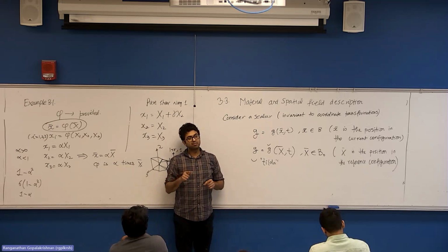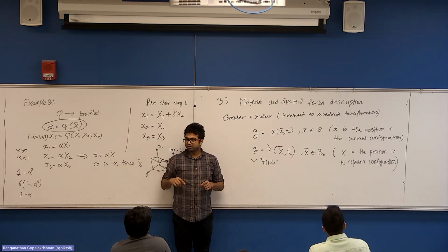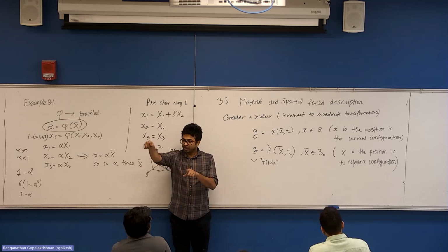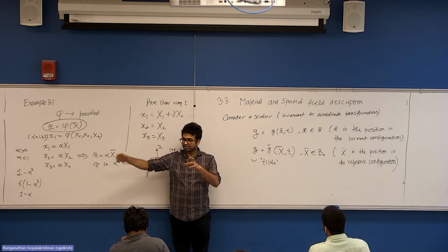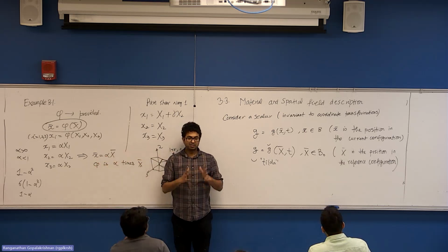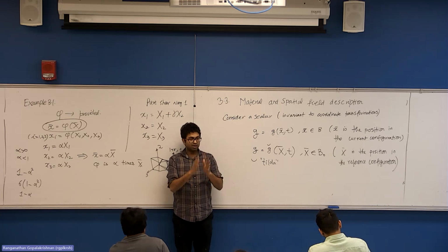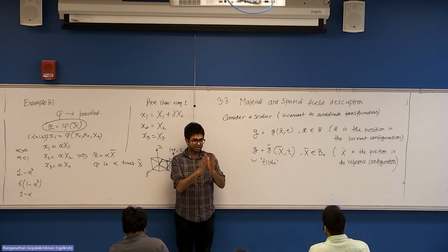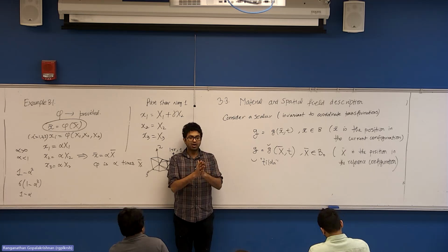If I want to know the temperature at some other point, what should I do? Bring another thermocouple, put it at another point so that I get a readout at 2 different points, 3 different points, or n different points. Okay, this idea is Eulerian. Eulerian means space focused. I am interested in space at a point, not about matter or material.